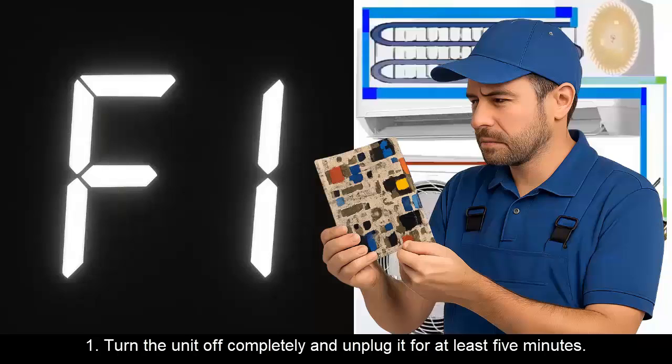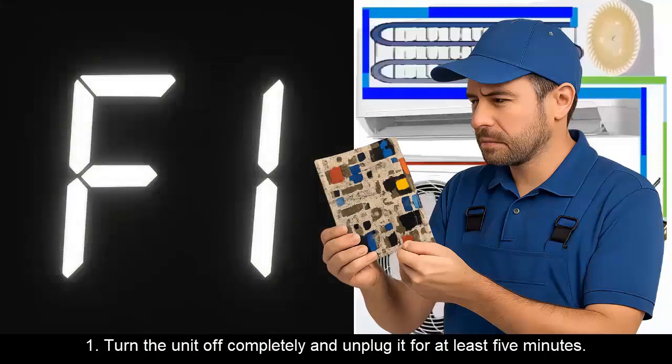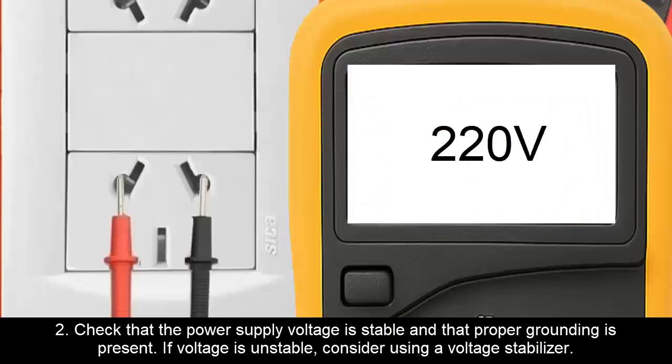1. Turn the unit off completely and unplug it for at least 5 minutes. 2. Check that the power supply voltage is stable and that proper grounding is present. If voltage is unstable, consider using a voltage stabilizer.